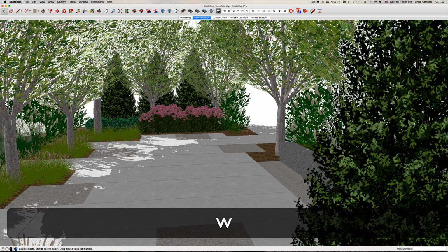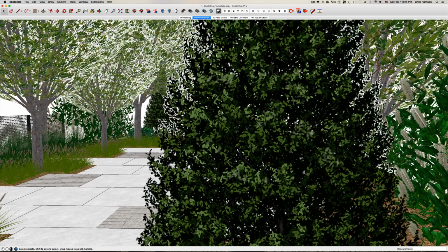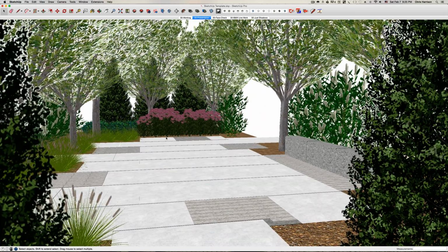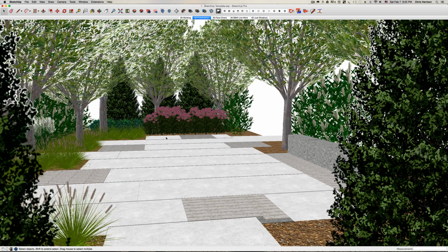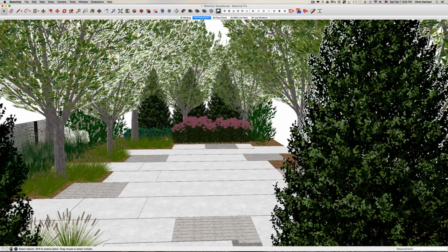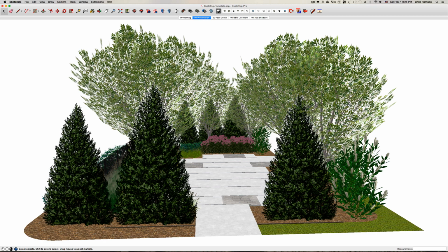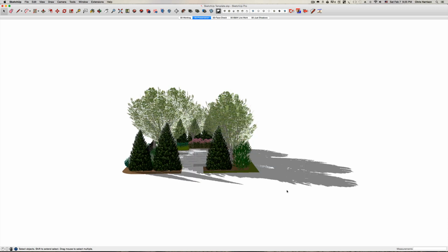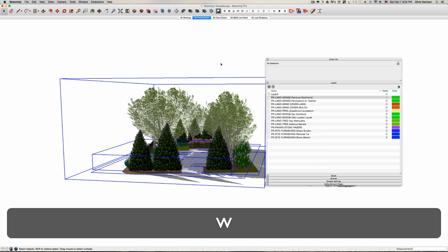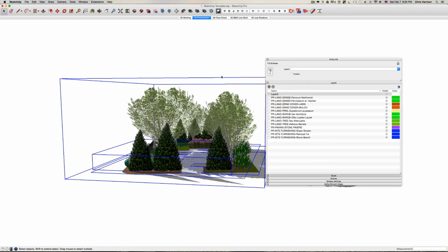And then from this also, let me just clean these windows up. And from this you can shoot shots now and do shadow studies and take this into our rendering programming and produce really high quality video and stills. Alright, so let me do a zoom extents. Zoom out some. I'm going to select the whole thing and make sure that my windows are back on. I'm on layer 0, and I'm just going to make the whole thing a group as well, because we're going to end up inserting this into the context model. So I'll make that all a group.